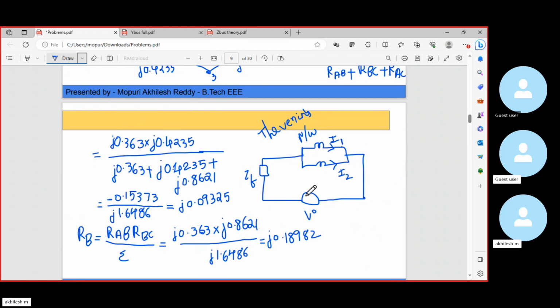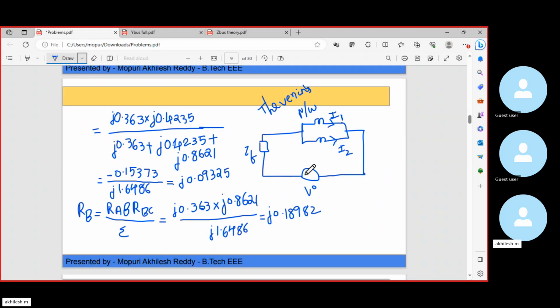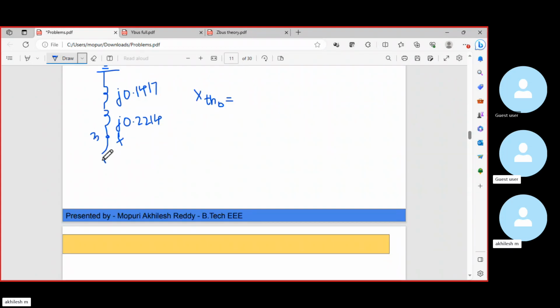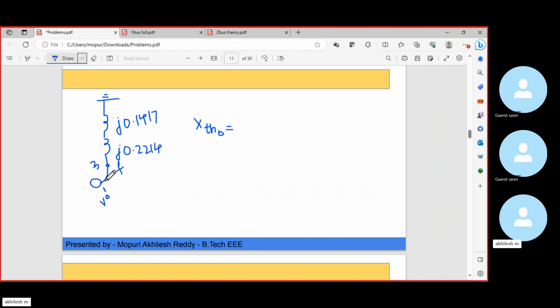Okay, here we have the pre-fault voltage. The fault point is connected to the negative of the pre-fault voltage V0. If we see the previous symmetrical fault analysis using Thevenin's theorem method, the fault point should be connected to the negative terminal of a voltage source of the pre-fault voltage, and the positive terminal should be connected to ZF and the ground.